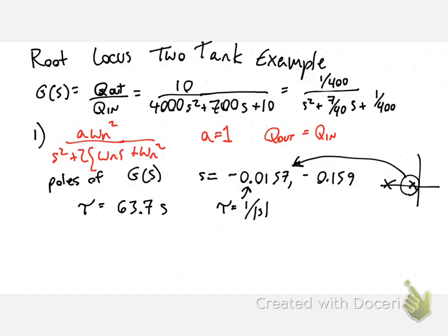And we are given the task that we want our settling time to be within 30 seconds. So we would like Ts, and I'm going to say it's for 5%, to be equal to 30 seconds. And we would like our Mp to be equal to 16.5%. So for this, underdamped second order systems are typically much faster than an overdamped second order system. And it's going to be easier for us to create this by simply using an underdamped second order system form.